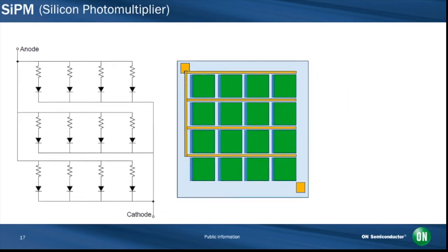Now let's consider the output from an SiPM. When a microcell in the SiPM fires in response to an absorbed photon, a Geiger avalanche is initiated, resulting in the same cycle of breakdown, quench, and reset as we saw for the SPAD. The output signal caused by the firing of this microcell is available from the anode or cathode. Each microcell detects photons identically and independently. During a microcell's avalanche process, all of the other microcells will remain fully charged and ready to detect photons.